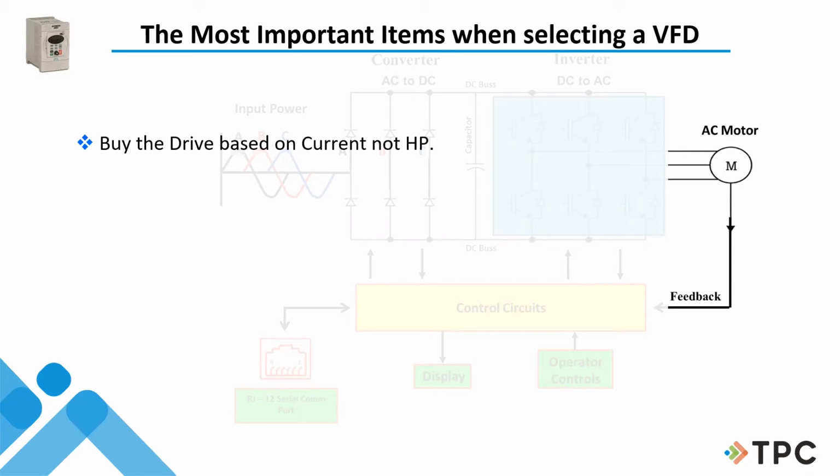And probably of that 60%, 80% of them don't have the right overloads or fuses or breakers in them to help protect them. So before you buy a 20 horsepower drive because you have a 20 horsepower motor, you better find out what it's really doing. A lot of times it's doing a lot more than 20 horsepower worth of work.